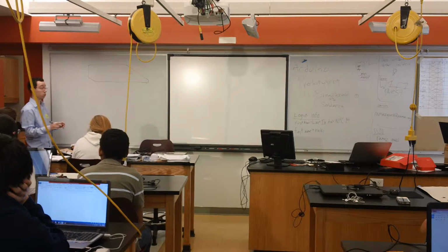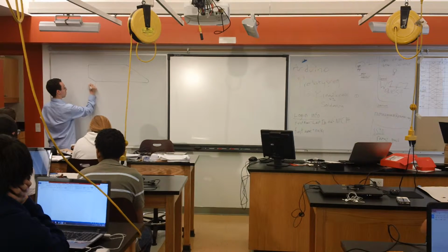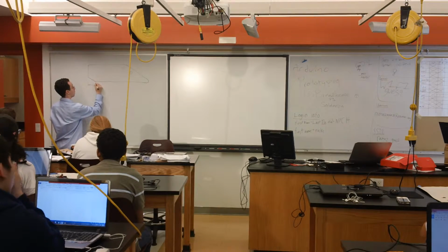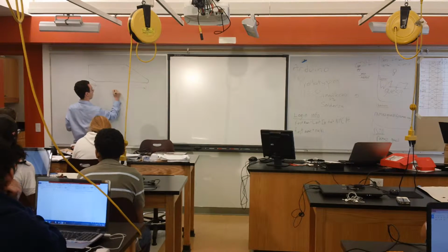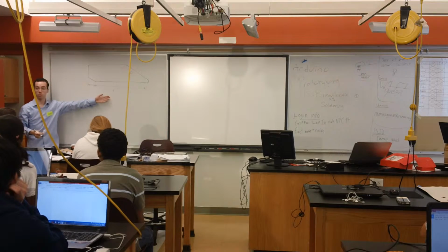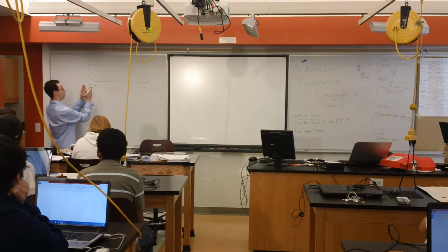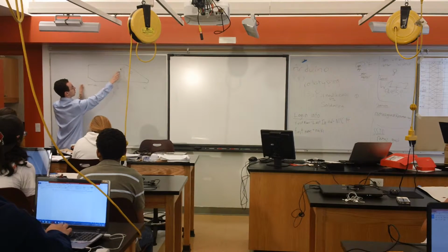One is what we call chain dimensioning, where I pick a starting point and I say, okay, this is 1 inch away from my starting point, and then I can say, okay, whatever it is, this is 6 inches away from the end of that. That's what we call a chain dimension, where actually what I should have done is gone from here, then said this, let me do that.